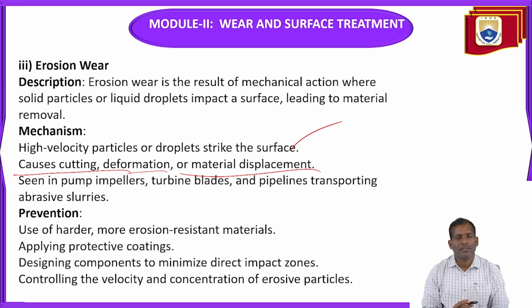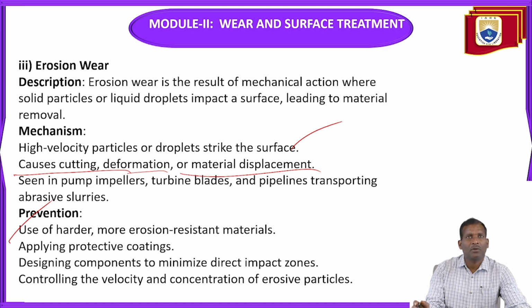How to prevent this type of erosion wear? Use hardened material in place of softer material, and more erosion resistant material is required. So use very hard material. More strength is required, so whenever the particles are impacting on this surface, they will not affect it.